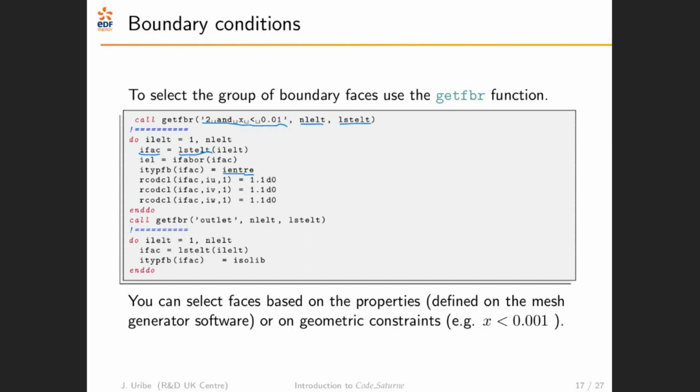The same way the grid doesn't have a normal vector for the face, for example. So Saturne computes the nodes that create a face. So if it's a triangular face, it has the 3 nodes and computes the plane from those 3 points and computes a normal to that face and computes the face center. So all that is done at the pre-processing stage.